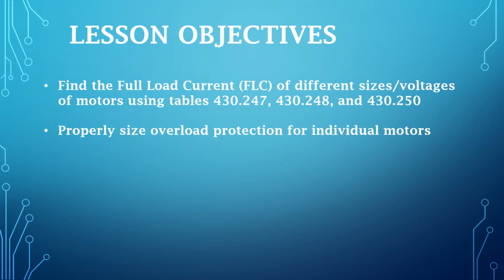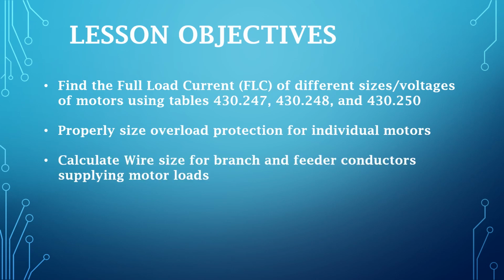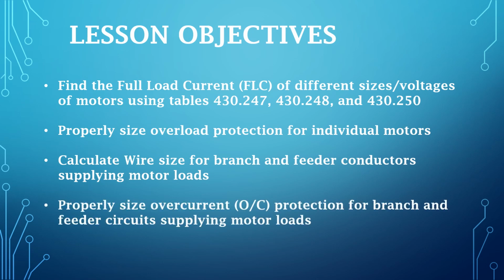We're going to properly size the overload protection for individual motors. We're going to calculate the wire size for branch and feeder conductors supplying those motor loads, and we're going to properly size the overcurrent protection, the breakers, for branch and feeder circuits that supply these motor loads.